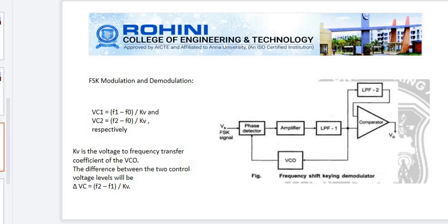So the reference voltage for the comparator is derived from the low pass filter used in the circuit diagram, and its output is midway between the voltages Vf1 and Vf2. Therefore, Vf1 and Vf2 at the comparator give an output V0 of 0 and 1 respectively.